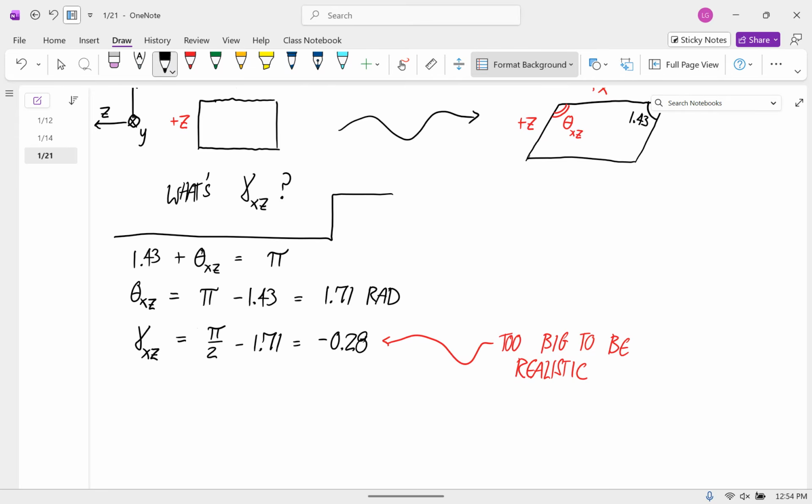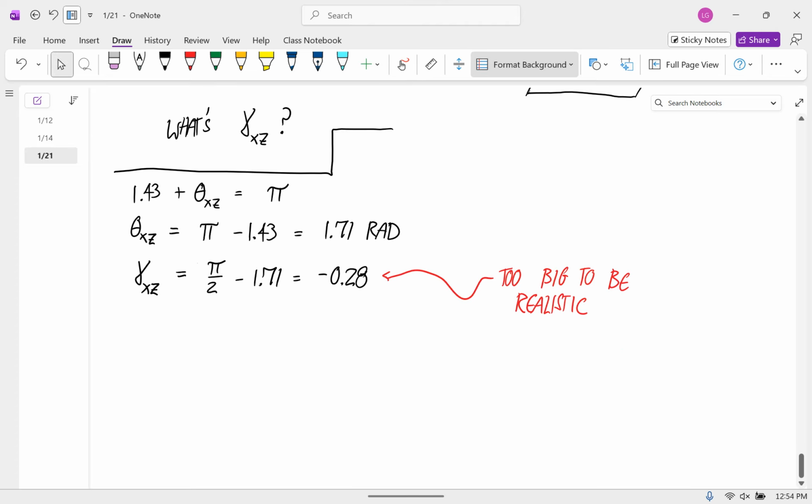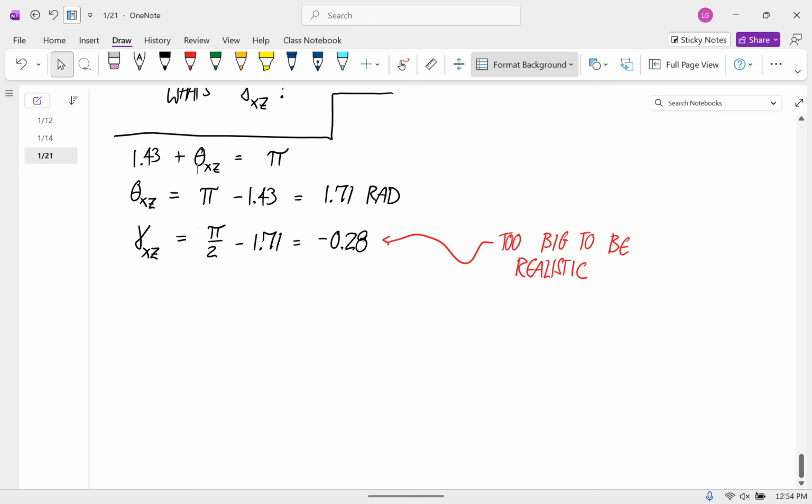And then how do we represent all the values of the strain? You might think that we would have a strain tensor and a Voigt strain because everything looks so similar between the stresses and strains. It turns out that the way we're defining strain, it doesn't meet the mathematical requirements of a tensor. So all we're going to use is the Voigt form.